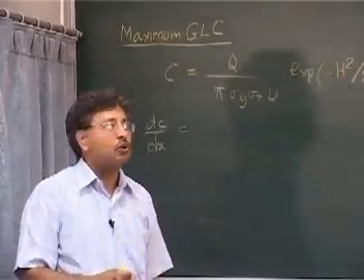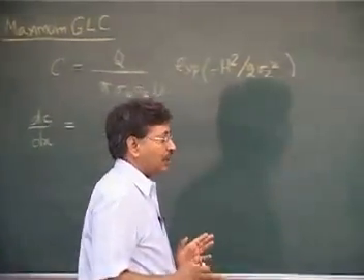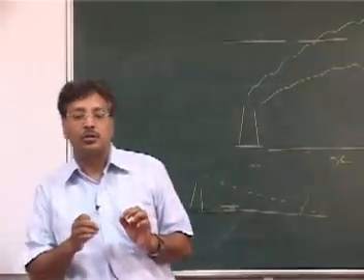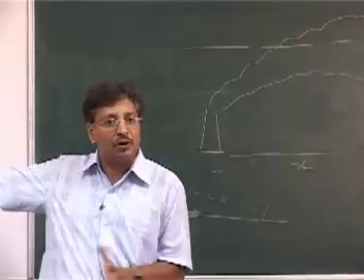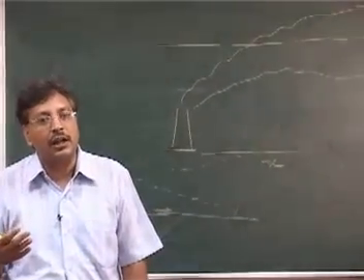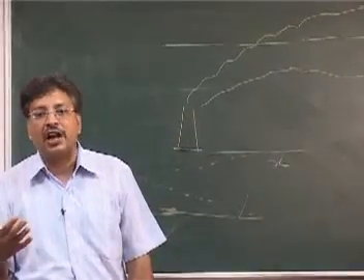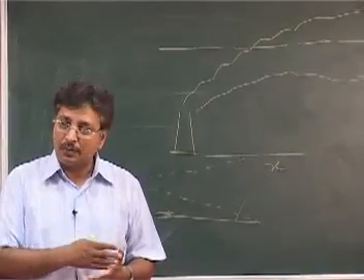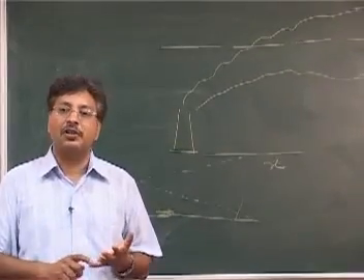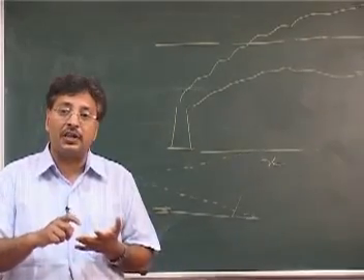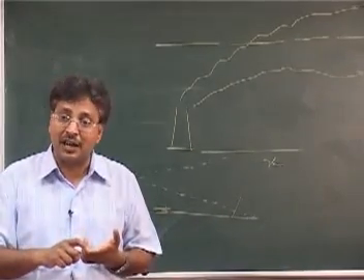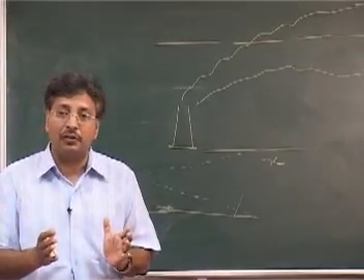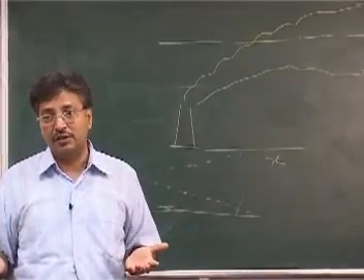Okay, but it is true that you can do it for 24 hours, and if you want to get more accurate results, then you model hour to hour. You supply the data to the computer, because simple calculations we can do on the board, but if you want more precise, more accurate concentration predictions, then you have to use computers and supply the data: every hour what is the wind speed, every hour what is the wind direction, every hour what is the stability class, every hour what is the mixing height, and then you can use the model. And then of course if you want to find out the 24-hour value, you have the 24 data points, one for every hour, and take the average of that.